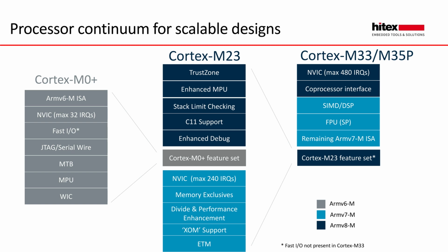data regions. Now, this we can sort of create as a dialog, and underneath the tool then creates the linker scatter file, which is the linker input file. Now, ultimately, we're going to create the scatter file with a separate tool that we'll look at later. So for these projects, these menu options are disabled, and we'll see how that's done in a little bit.